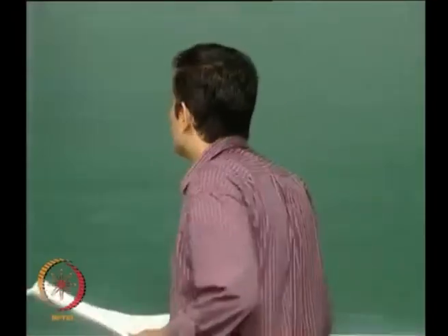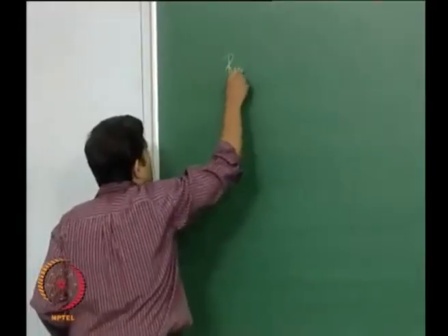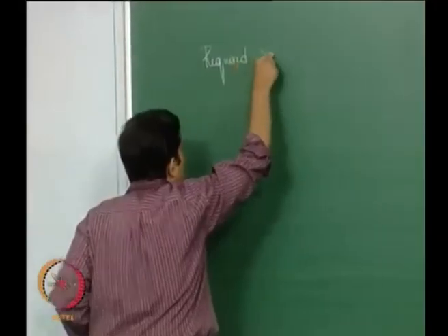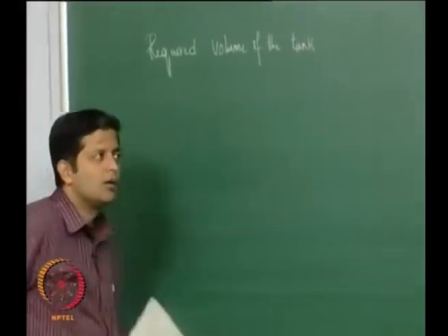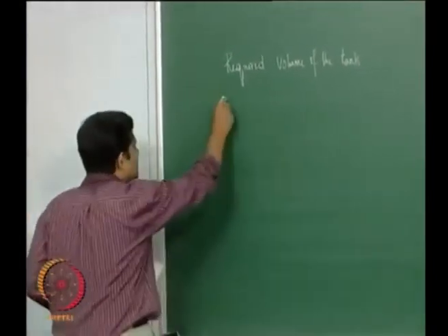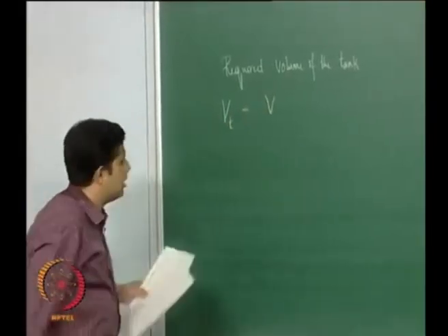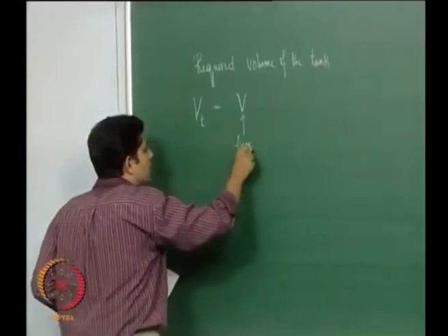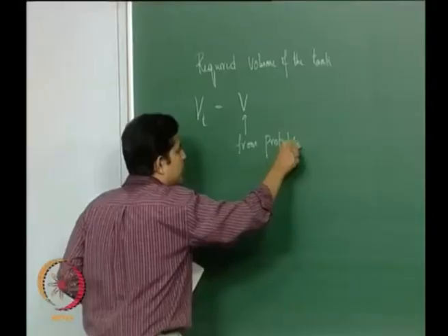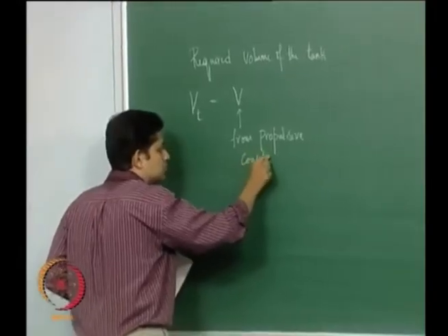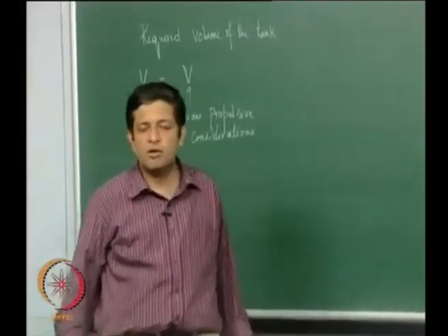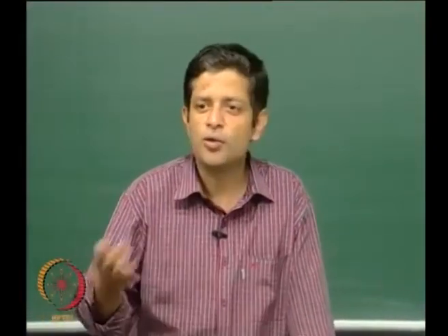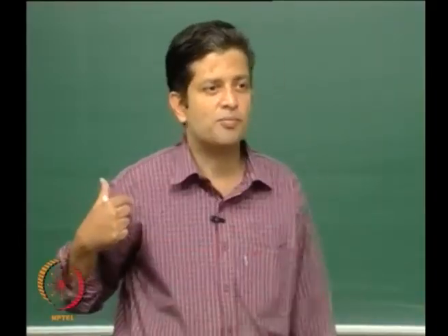Before we go there, just to refresh the required volume of the tank, this will have to include the volume calculated from propulsive considerations, that is, if you are looking at the mass flow rate from thrust, knowing Isp, calculate mass flow rate, and then knowing density of the propellants and the burn time, you can calculate volume, right.